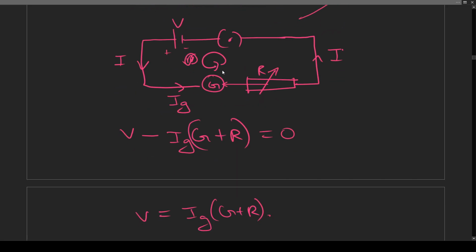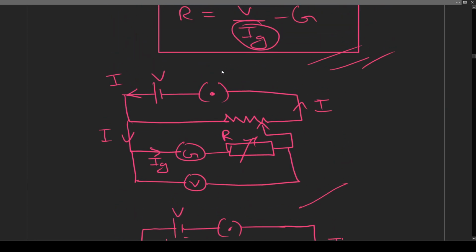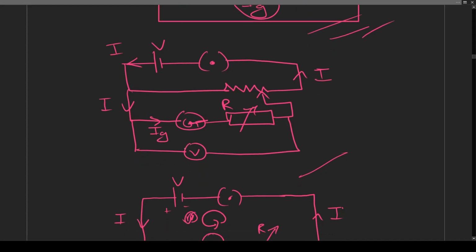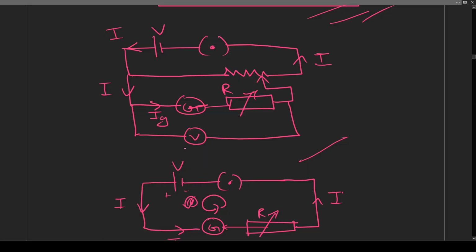After we plug R amount of resistance from this resistance box, this galvanometer should show a full scale deflection. Normally, because there will be errors in the resistance box, apparatus and even our calculations, it will sometimes show a slightly lesser deflection than full scale deflection.